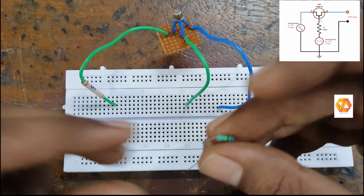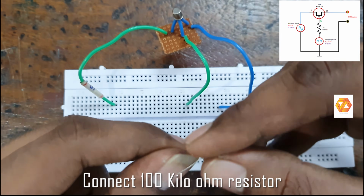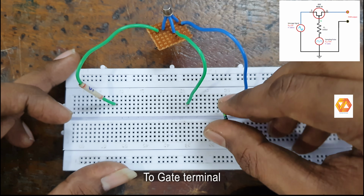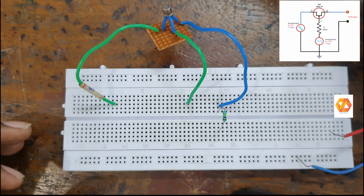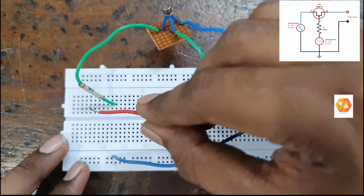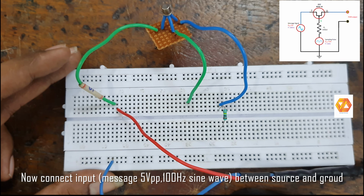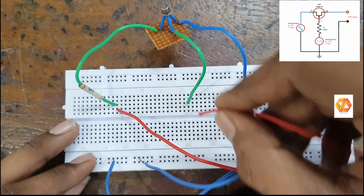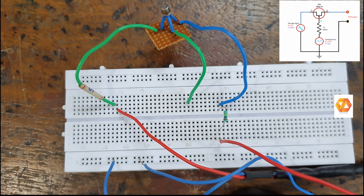So on the right side you can see the gate terminal. This is the 100 kilo ohm resistor. Connect it to the gate terminal. Here we are giving a message signal, that is the modulating signal, as a sine wave with 5 volt amplitude and 100 hertz frequency. Now connect the input message signal and then connect a sampling pulse, that is our carrier, whose amplitude is 15 volt and frequency is 1 kilohertz. Connect it to the gate terminal through a 100 kilo ohm resistor.